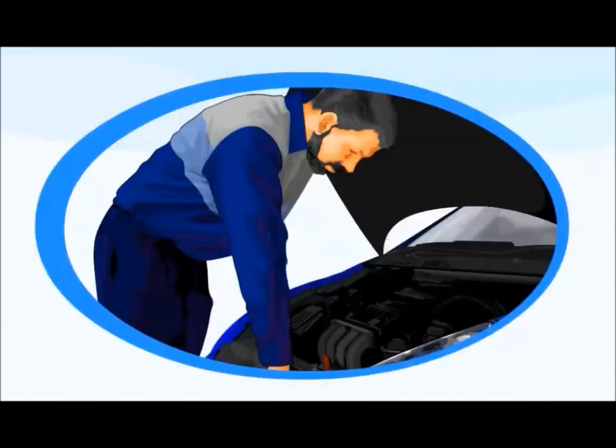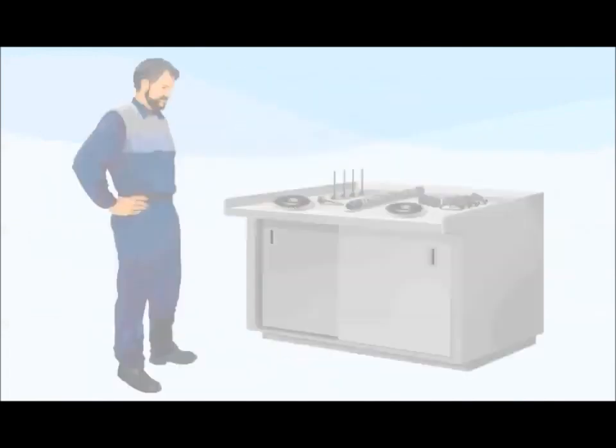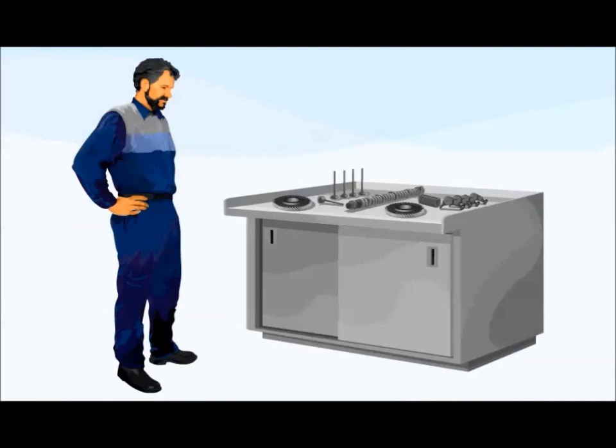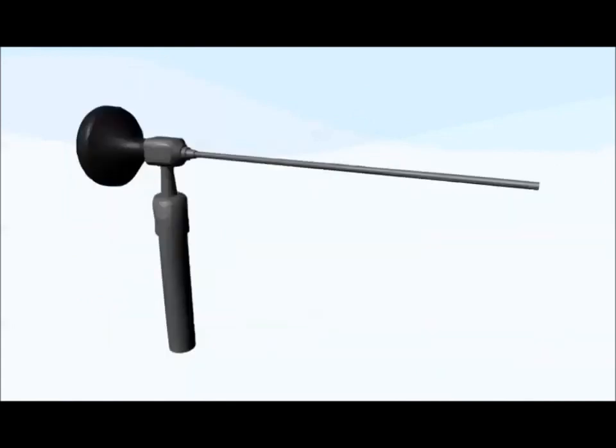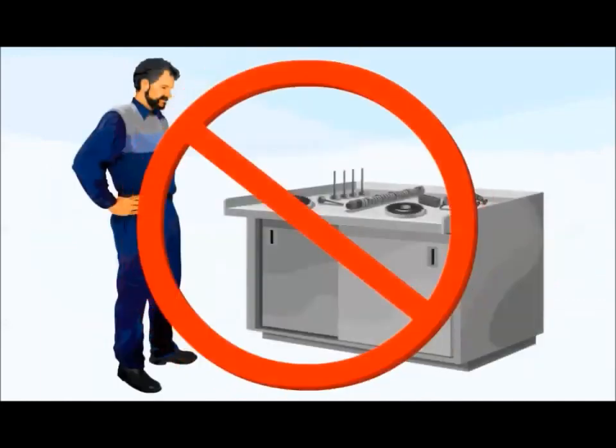Technicians always have the option to disassemble the engine to perform internal checks, but this approach is time-consuming and doesn't always locate the problem. To help prevent these problems, a tool called a borescope allows technicians to inspect internal engine parts without disassembling the engine.